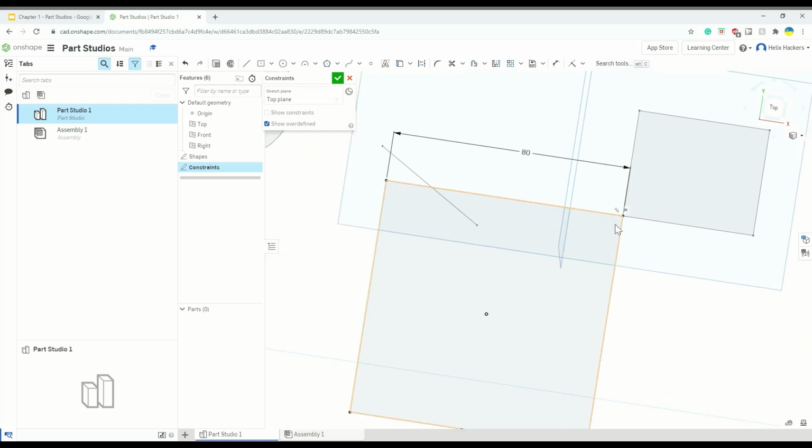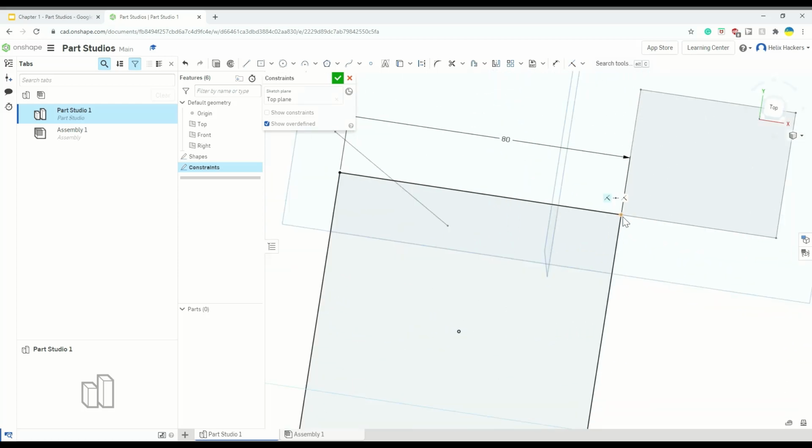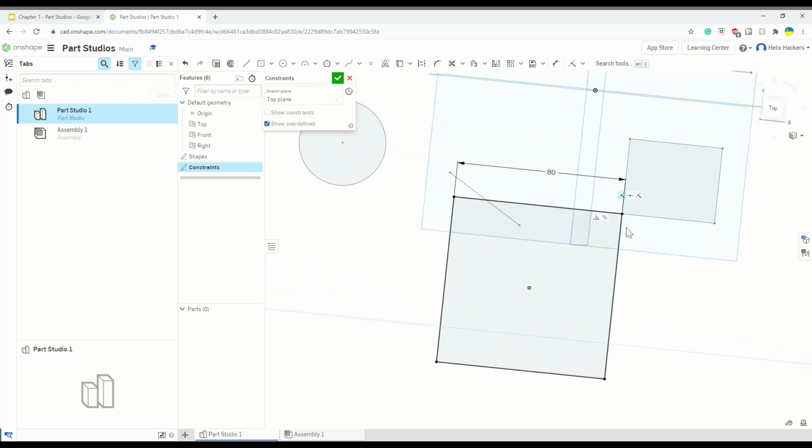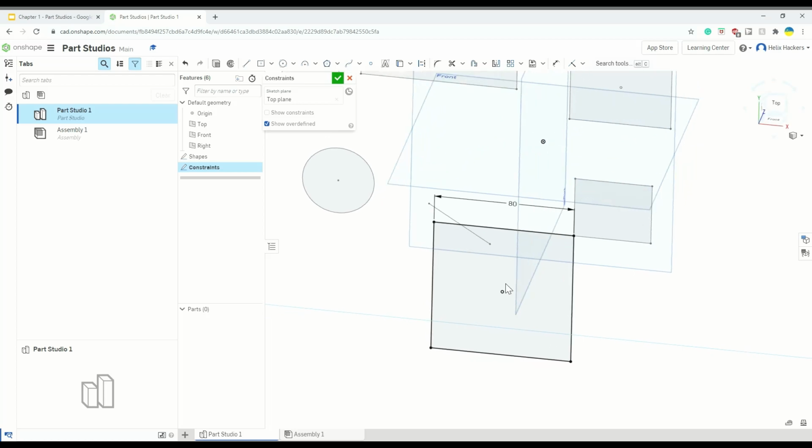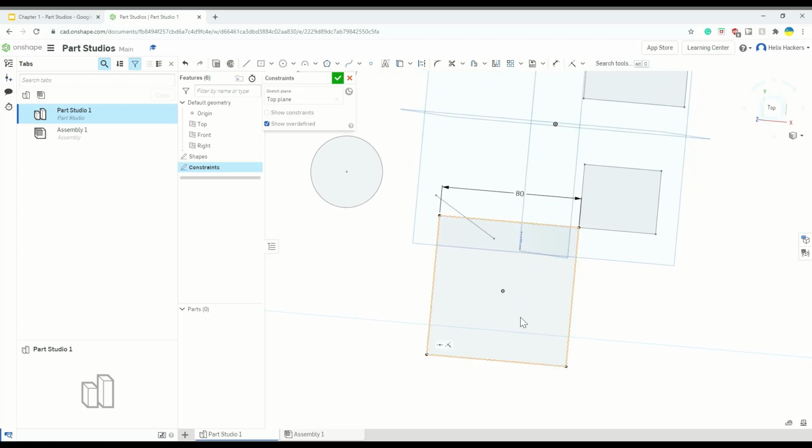So now this is fastened onto this point, thus it's coincident, and as you can see, the sketch has turned black. This is because we've defined all the positioning and the lengths and the dimensions of the sketch, meaning it cannot be changed unless you manually change the values. So we've basically fastened this sketch. This is normally what you want to see when you're designing parts, because this means it's nice and defined and there's no room for error.